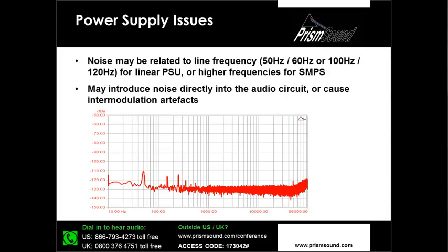And here's just a quick example of an FFT of a device that has a power supply related problem, and we can see here that there are a number of harmonics clearly visible in the spectrum at the 50 Hz mains frequency and its harmonics.